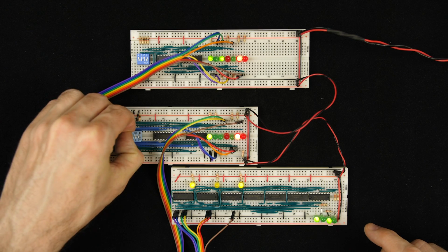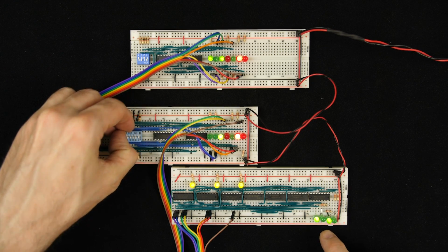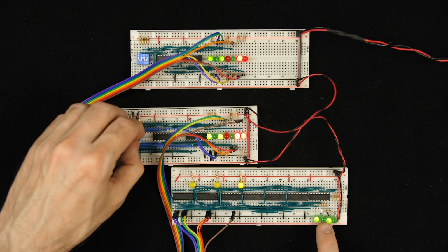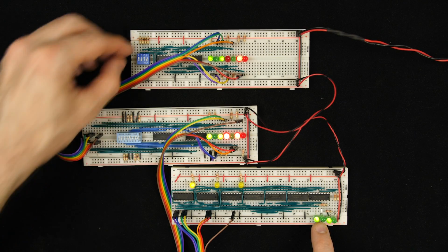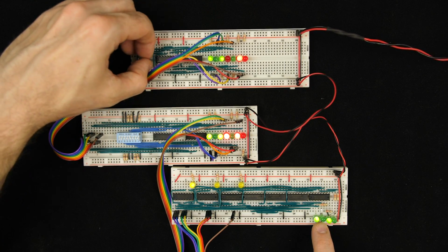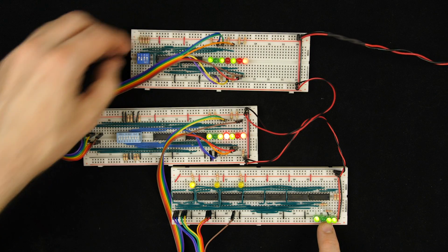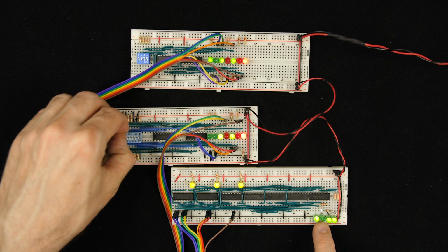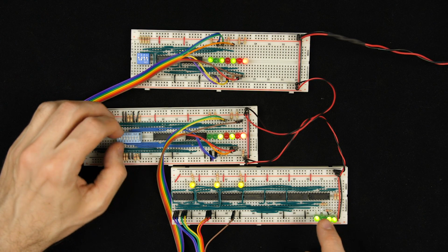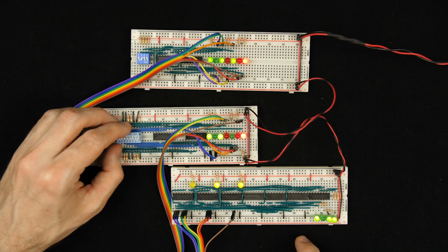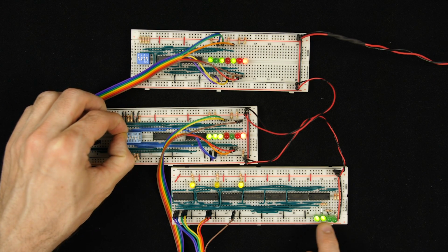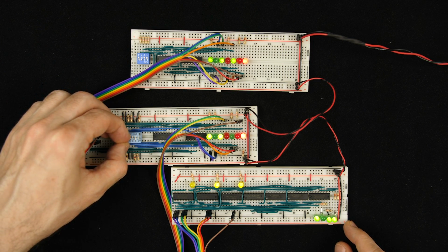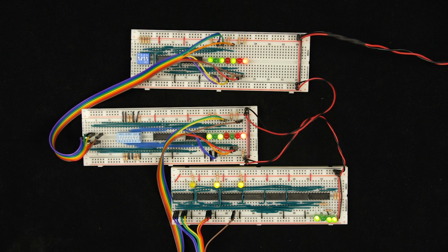If we start introducing other errors, what we see is that regardless of which bit error we introduce, the output remains the same. And of course, if we change the input, that'll change the output. The output will always match the input. But if we have any single bit error, our output doesn't change. We're correcting that error. Of course, if we have 2 bits of error, then the output changes, but that's just not something the circuit guarantees. This is only able to correct a single bit error.